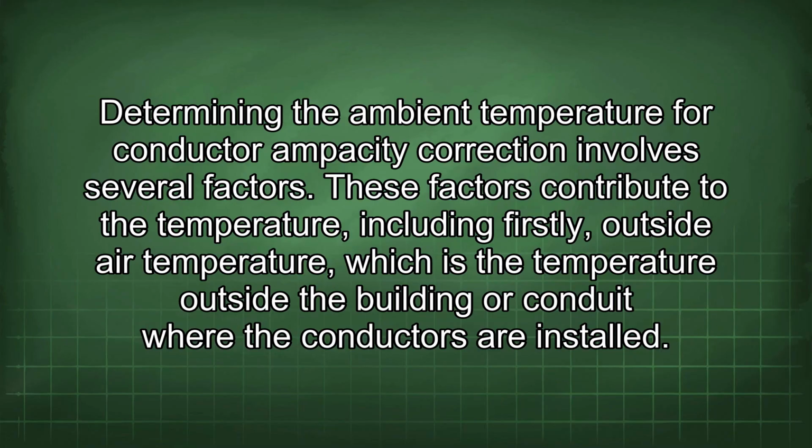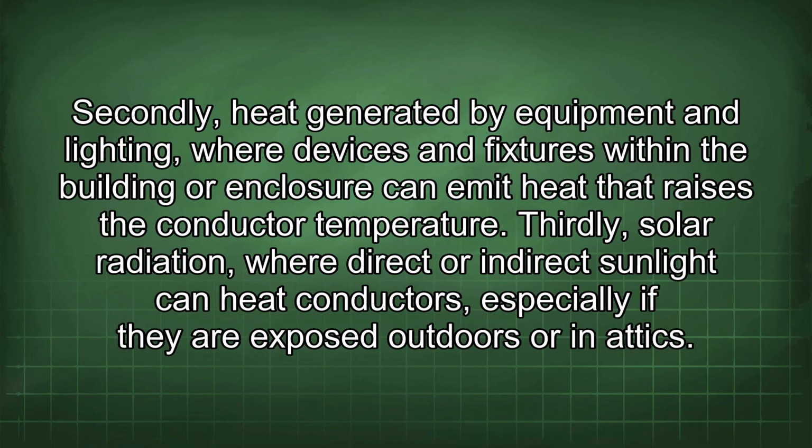Determining the ambient temperature for conductor ampacity correction involves several factors. These factors contribute to the temperature, including, firstly, outside air temperature, which is the temperature outside the building or conduit where the conductors are installed. Secondly, heat generated by equipment and lighting, where devices and fixtures within the building or enclosure can emit heat that